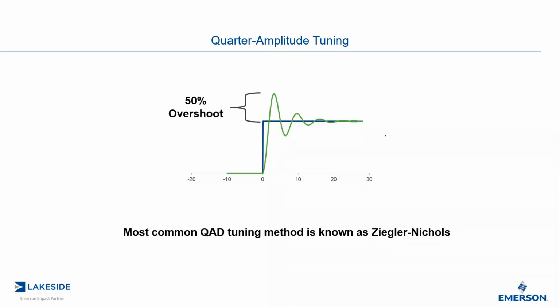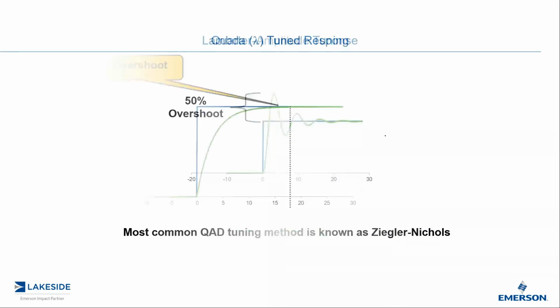We know that our process will change, and we know that the tuning must match our process. So, short of retuning a process for every possible different condition, be it summer, winter, different production rates, different grades, or even just the type of process itself, we must build some robustness, some ability of our control to remain stable, even though our process may change over a period of time. So that's what robustness means. And Ziegler-Nichols is not a very robust type of tuning.